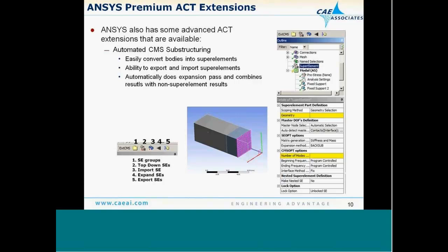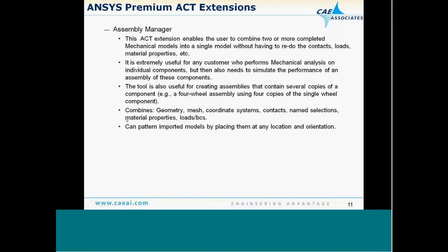Some extensions that are not up there, but they're ones that ANSYS has developed. This one allows you to do component mode synthesis in Mechanical. So you can create super elements from different bodies, and then behind the scenes it does a generation, use, and expansion path for those super elements. So this is a rather involved extension, call it a premium extension, but this was one that was developed for a particular customer. Another example of this type of extension that was developed for a customer was an assembly manager.